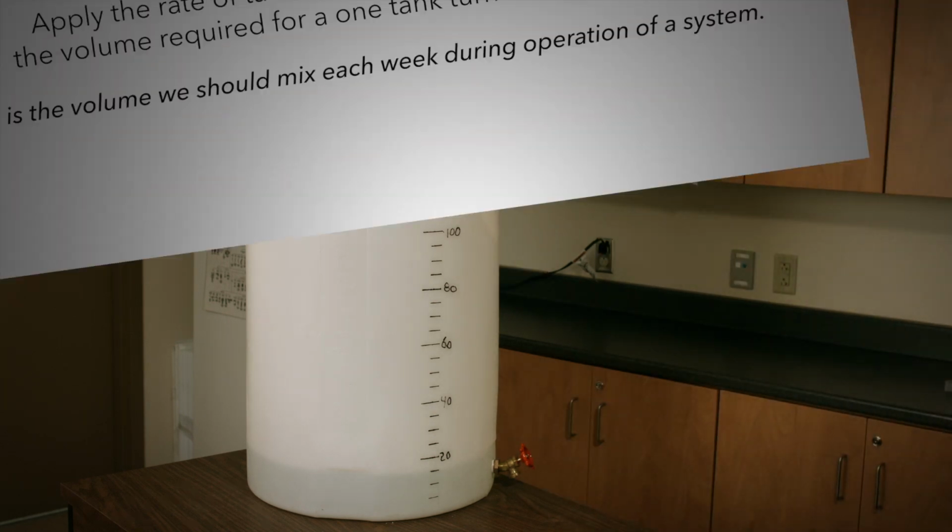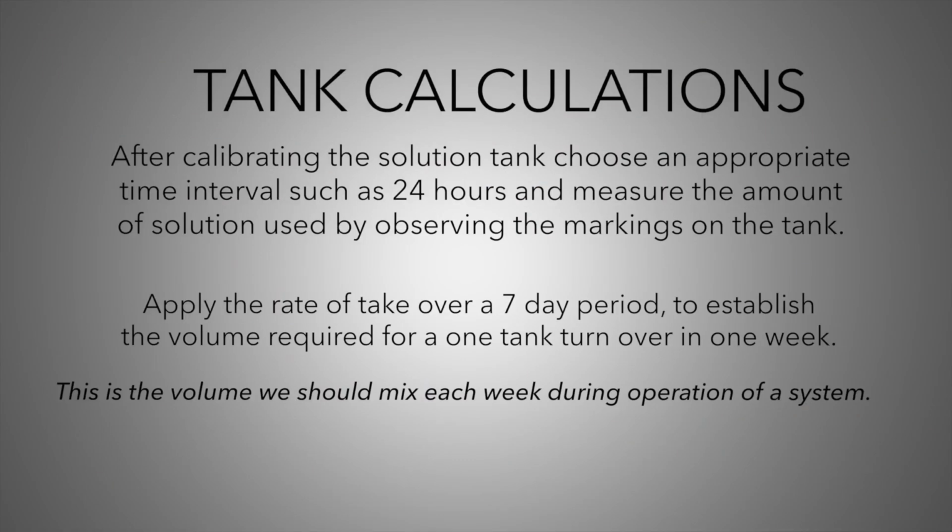Choose an appropriate time interval such as 24 hours and measure the amount of solution used by observing the markings on the tank. Apply the rate of use over a 7-day period to establish the volume required for a 1 tank turnover in 1 week. This is the volume we should mix each week during the operation of a system.